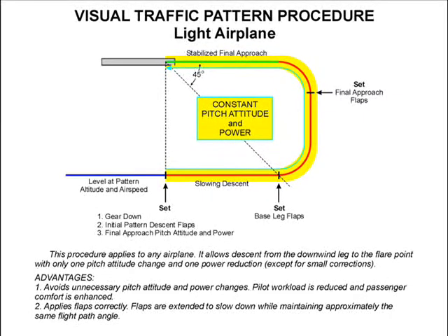This procedure applies to any airplane. It allows descent from the downwind leg to the flare point with only one pitch attitude change and one power reduction, avoiding unnecessary changes. Pilot workload is reduced, and passenger confidence and comfort is enhanced.